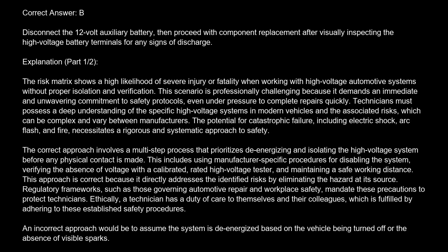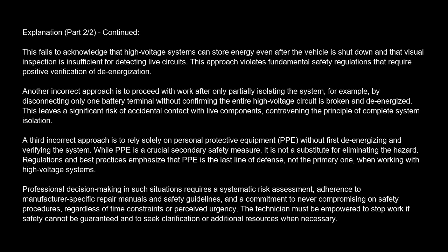An incorrect approach would be to assume the system is de-energized based on the vehicle being turned off or the absence of visible sparks. This fails to acknowledge that high-voltage systems can store energy even after the vehicle is shut down, and that visual inspection is insufficient for detecting live circuits. This approach violates fundamental safety regulations that require positive verification of de-energization.